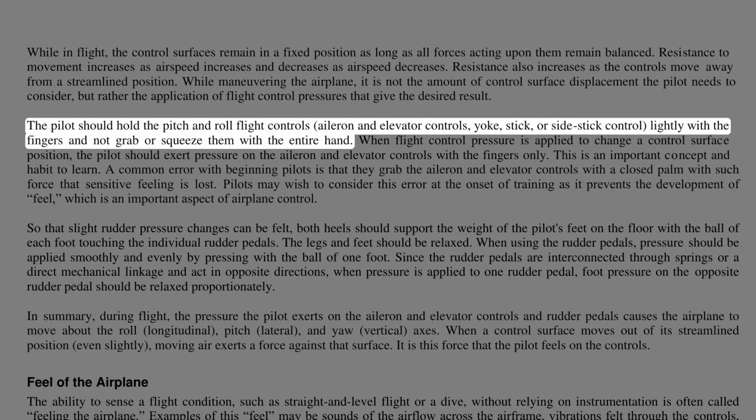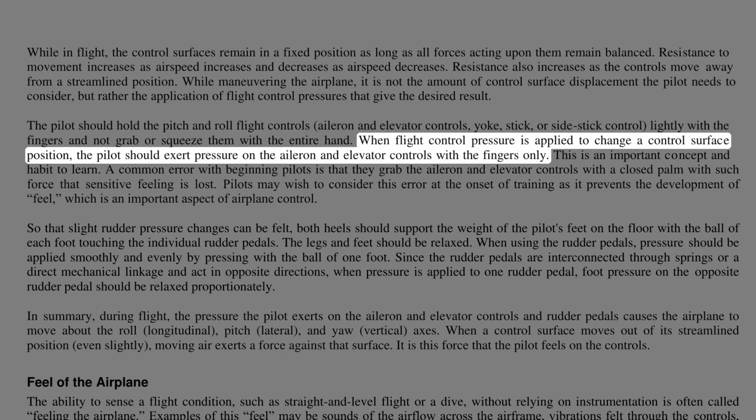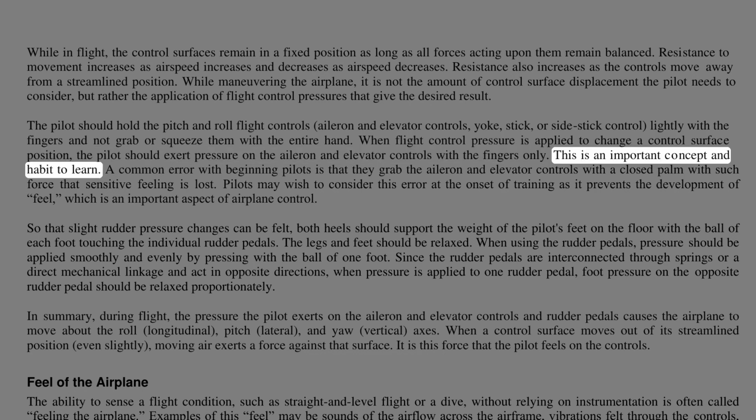The pilot should hold the pitch and roll flight controls, aileron and elevator controls, yoke, stick, or side stick control, lightly with the fingers and not grab or squeeze them with the entire hand. When flight control pressure is applied to change a control surface position, the pilot should exert pressure on the aileron and elevator controls with the fingers only. This is an important concept and habit to learn.